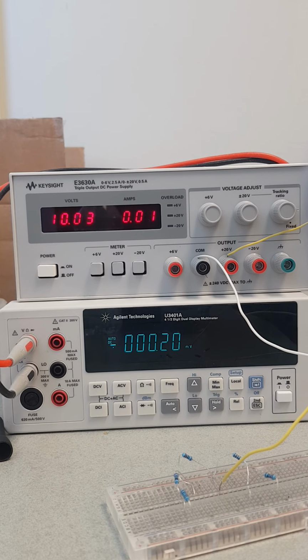However, for a sensor like the thermistor, which we will see again in the future, the change in resistance is significant. A small change in temperature will lead to a 20-30% change in the resistor. When the change is like that, any tolerance in the component will not impact the measurement as badly as when the change is very, very small.